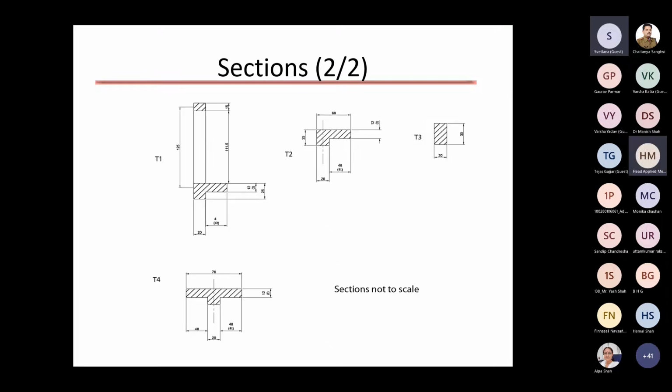And finally, this is continuation. This is for T elements, and T elements are the slab beam elements. So it is showing what the geometry of these elements is, and you can see these effective widths. For example, for this T4, you can see that effective width is about more than 70 centimeters, and the thickness of the slab is 12.